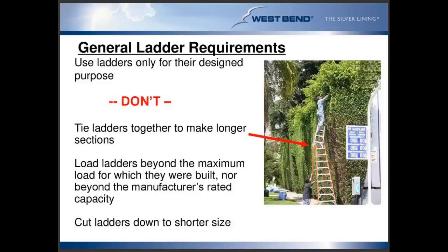One of the last bullet points there: cut ladders down to a shorter size. This is something that I run into quite often out in the field, where one section of an extension ladder may be damaged, but we figure, hey, let's keep the other section, it's still in good condition, but let's cut it down to size so we can use it at smaller heights.